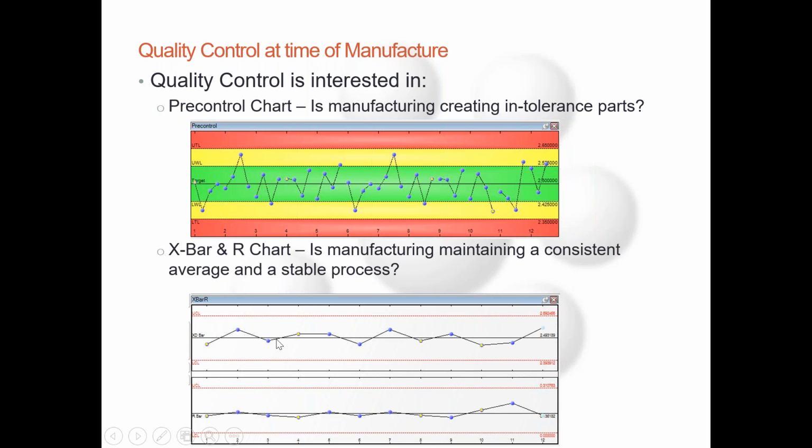So what each point on the X-bar portion of the control chart represents is the average of your subgroup. And that's why it becomes a more condensed form. That's why this could be hourly data, 2 data points per shift, looking at a few weeks or a month worth of data, while here we're looking at everything that's being measured on a continuous basis.